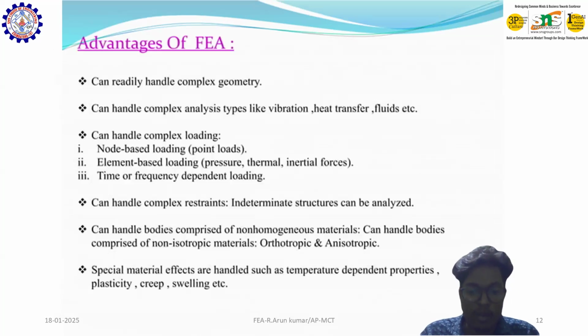So we have studied the meaning of FEA, the types of engineering analysis, the steps we carry out, and the phases required while doing FEA. Now these are the advantages. It can readily handle complex geometrical shapes. It can handle complex analyses like vibration, heat, fluid, fatigue, and structural analysis. It can also handle complex loads like node-based loads, such as point loads, element-based loading like pressure, thermal, and inertial forces, and time or frequency dependent loading.